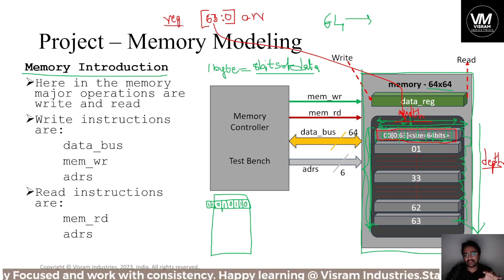In Verilog HDL, the data types are the key terms where you are representing the information or representing the actual element of the design. Whether it is a register, whether it is a wire, is it an input, output, or are you starting a procedural block like always block or initial begin block? Are you initializing the data, or are you starting a case statement? And also you can write functions out of it.